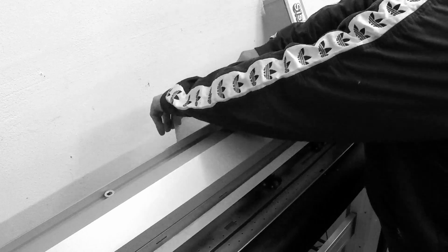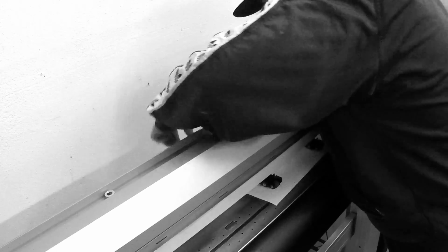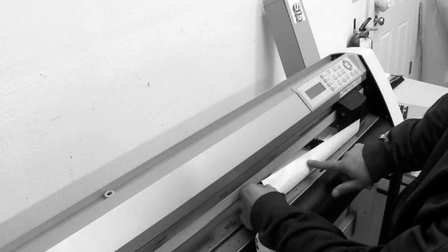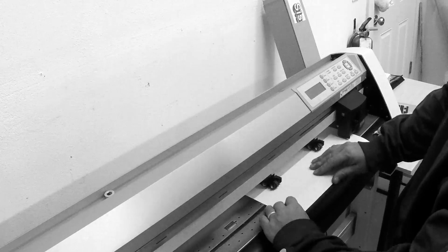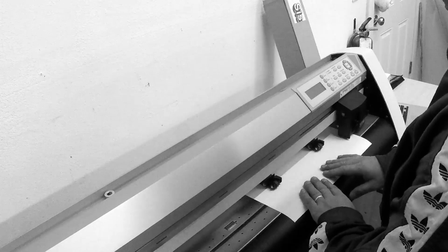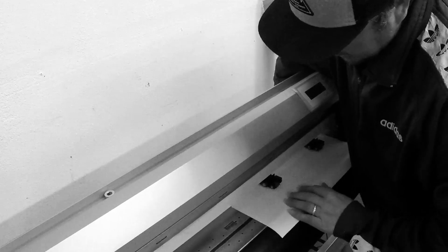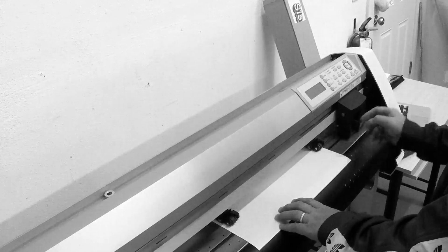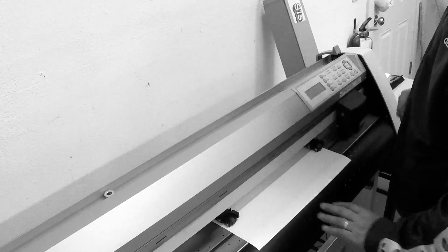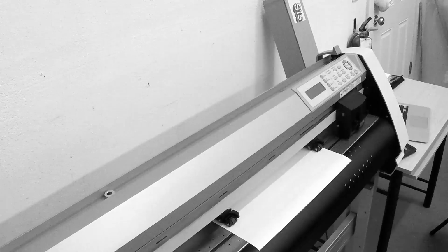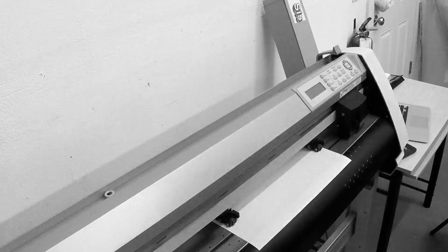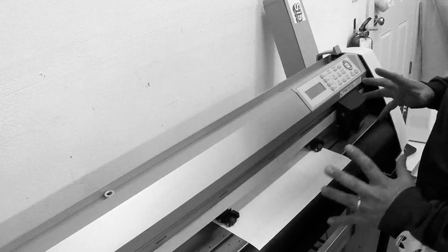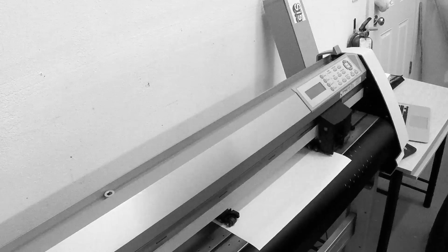All right, so here we're on the vinyl cutter. We have the material rolled up here in the back, and we want to feed it through this way. The material has a shiny side and a vinyl side. You want the vinyl side on top because that's what we're going to cut. You align it just like that, move the rollers over. Okay, looks pretty good. We're going to drop the rollers. They're currently pinching the vinyl now. And we're going to hit enter on here so that it can set itself up.